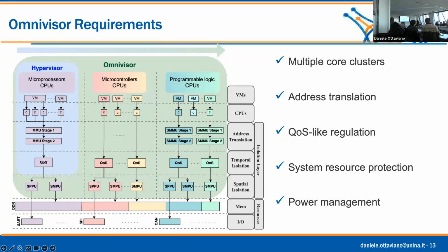So remind me what the RPU is. The Real-time, small microcontroller. Okay. Yeah, the Omnivisor takes care of that too, right? Exactly. So when the virtual machine is created and the MPU is programmed, if you launch code on the RPU, you also program an MPU that disables the access from the RPU to the MPU, so it cannot change its own permissions.